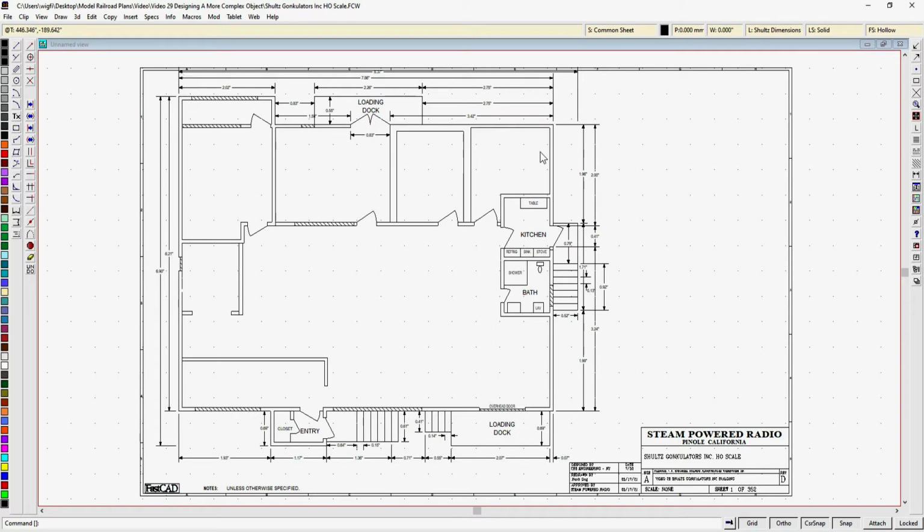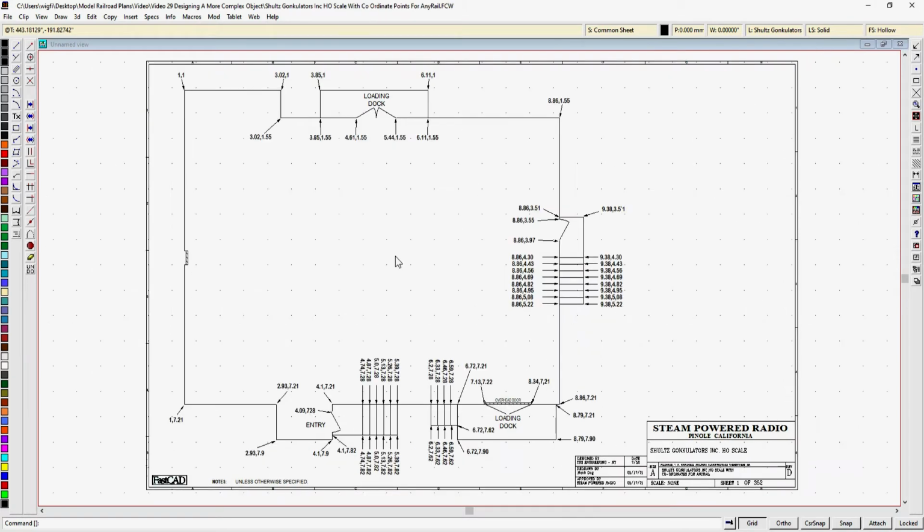So what I had to do was this. I had to make another drawing in which I went in and set all of the important coordinates. Now this looks like an awful lot of work, and it was. That's because I was drawing this using just separate lines all the way around. Every step was a separate line. And then, as I pointed out in video 28, I could have used rectangles, which makes it a lot easier. So what we're going to do here is draw this entire building using rectangles, and we'll just cherry pick whatever dimension we need to make our drawing.